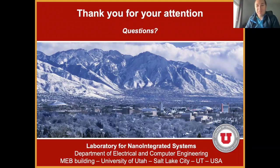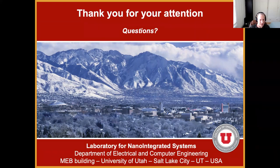I have one question about when you were talking, yeah, good talk, by the way. Good overview. When you're talking about static timing of the fabric, wouldn't it make more sense to have it be basically just characterization of the fabric? You characterize a single lookup table or things like that, and then you can abstract it from there rather than actually timing all of the paths through it. So it's a little different than digital design, right?